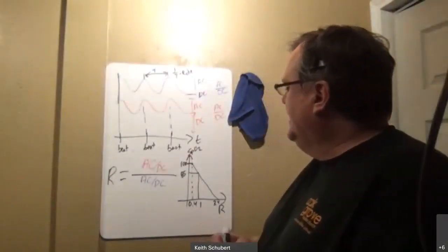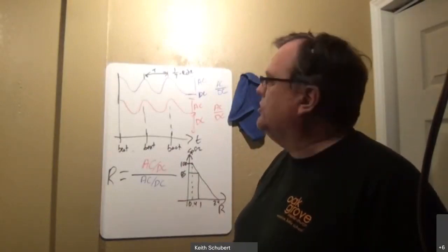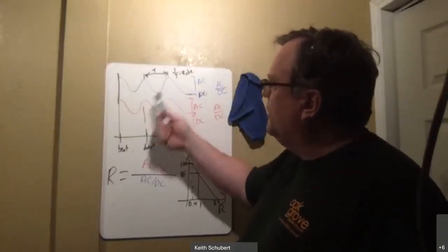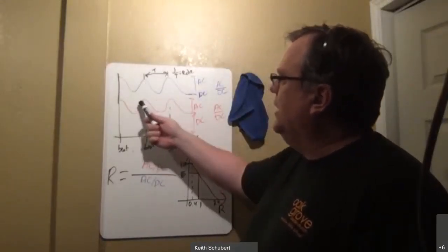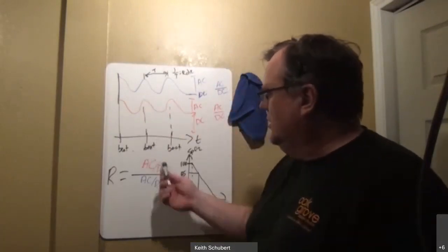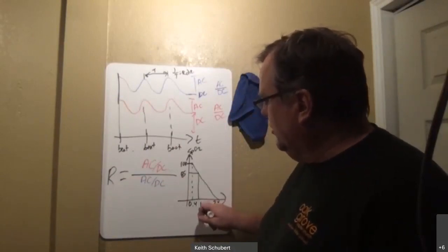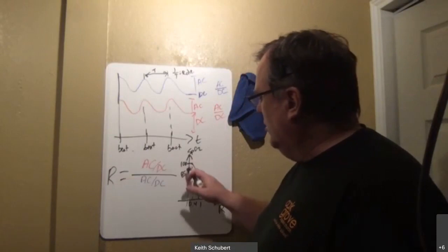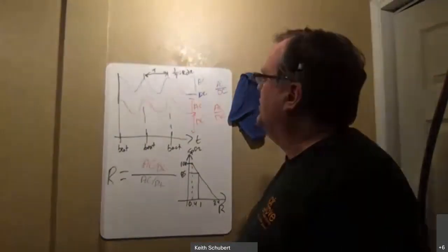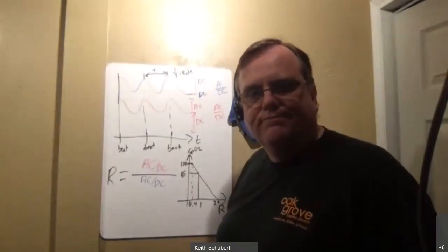All right. So, this is basically what's done on most pulse oximeters as a basic thing, right? Simple thing: two frequencies of light, measure it over time, find the max, find the min, calculate these values, calculate the ratio R, and then use this calibration curve to go from the value of R to the value of the oxygen saturation. And we can calculate other things like heart rate and things of that sort.